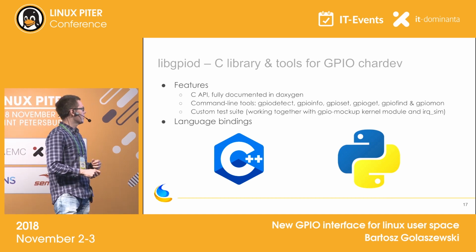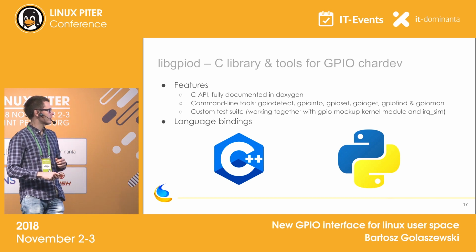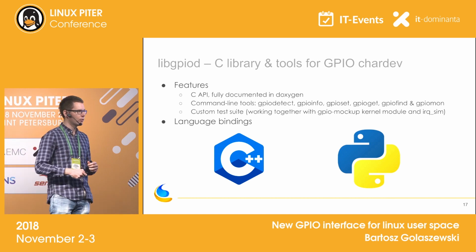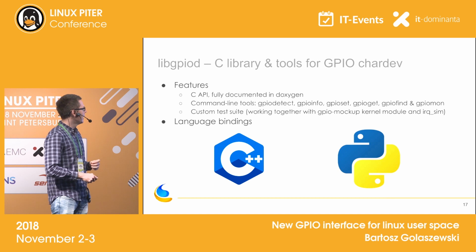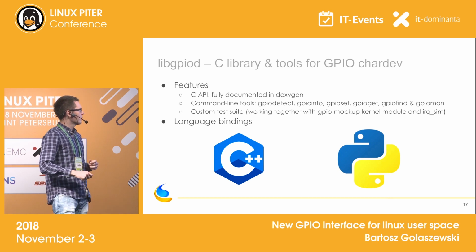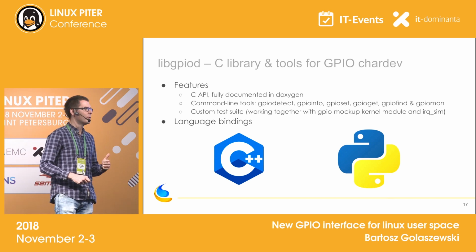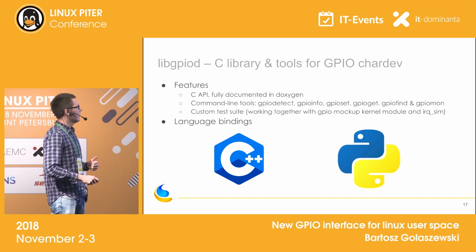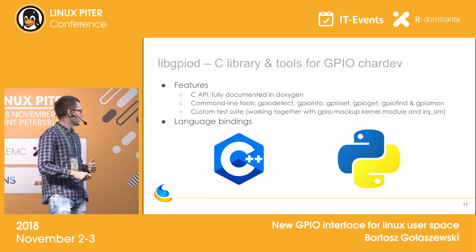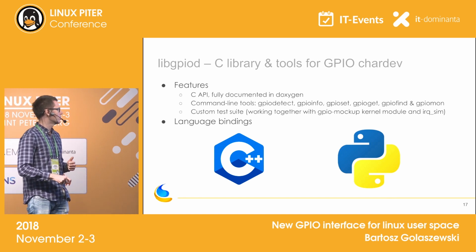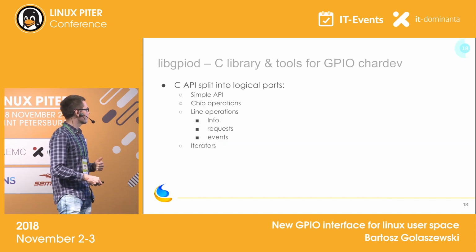from the kernel. We have a set of command line tools. This is interesting because this will allow you to replace all your scripts that deal with sysfs. We have a custom test suite. Again, we're working with the GPIO mockup module to test both the kernel UAPI and the library. We work with the interrupt simulator, and we have language bindings to C++ and Python.